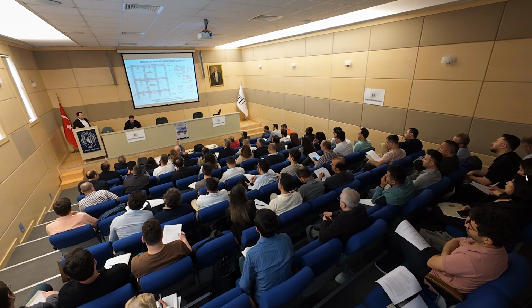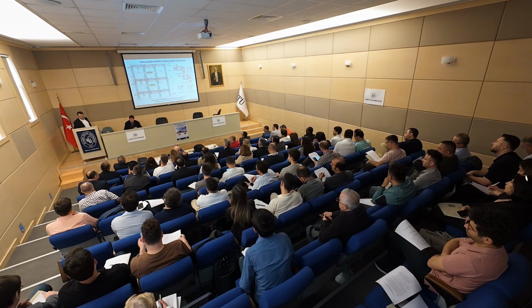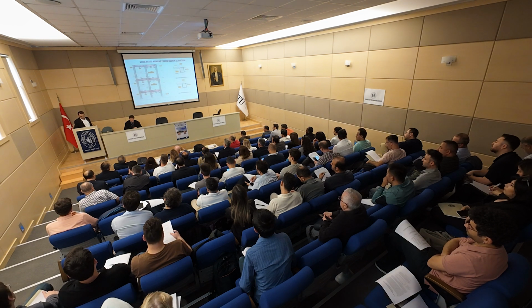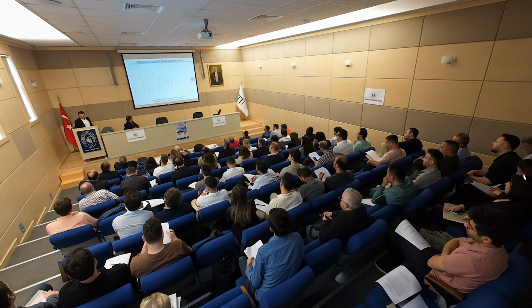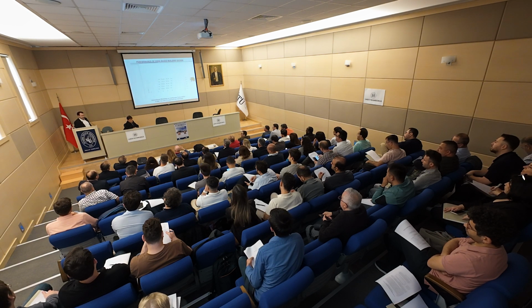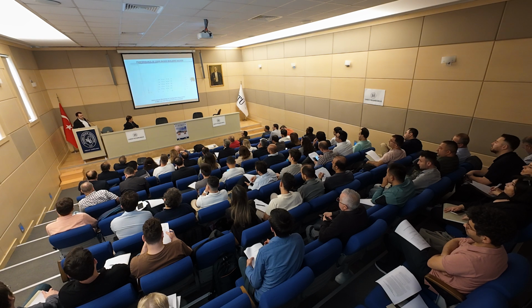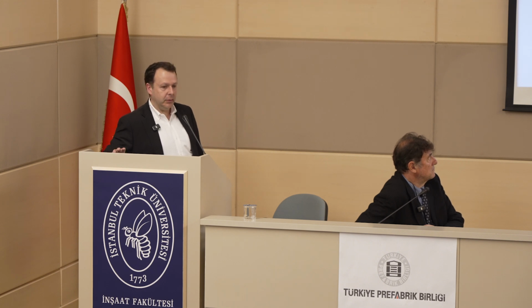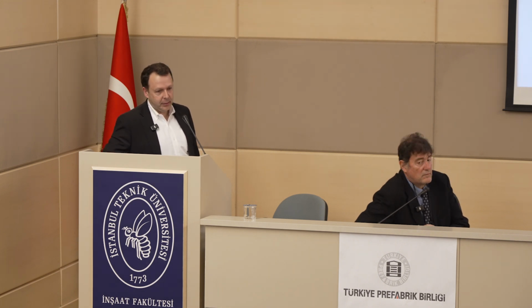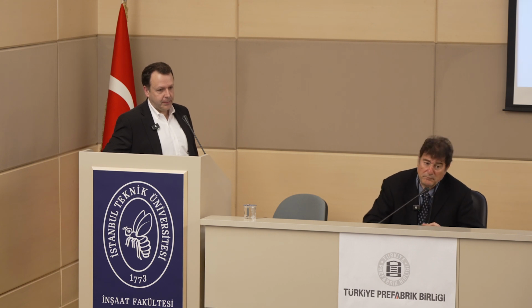I noticed on your deformation plot, you showed hinges at each floor. Don't you have a hinge at the base of the column? In this model, there was no hinge put at the base of the column. Yes, that would happen. The hinges were only put in the beams, but yes, you'd have a hinge also at the base. That was where they were allowed by the computer.